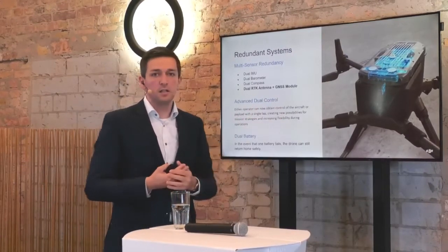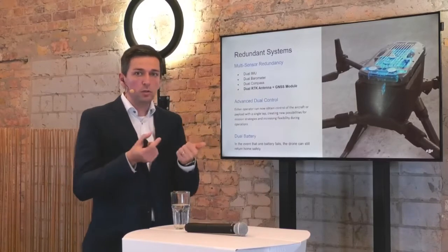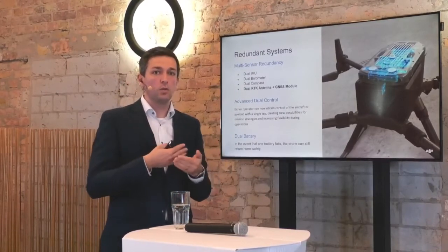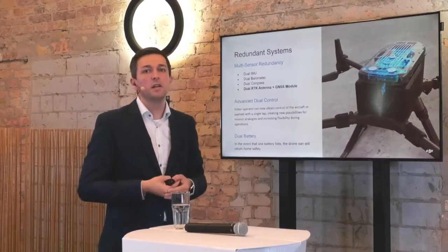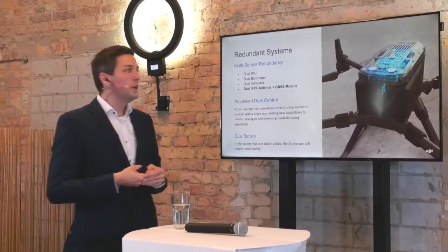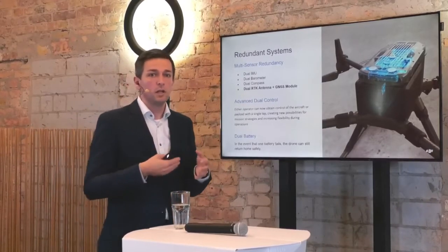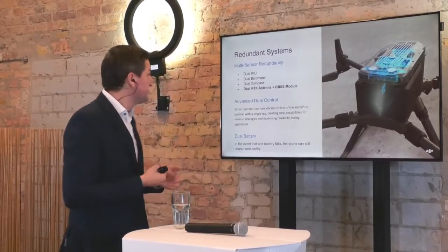This version has RTK information, which means you have dual GPS information and combine this with a base station network, which is very accurate. And that makes the positioning itself centimeter-level accurate, which is important if you want to map or generate digital terrain models or other geodata.